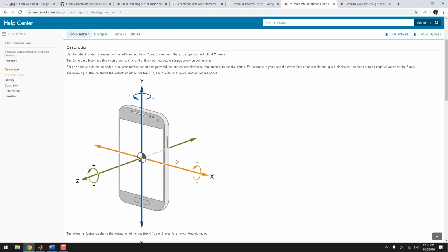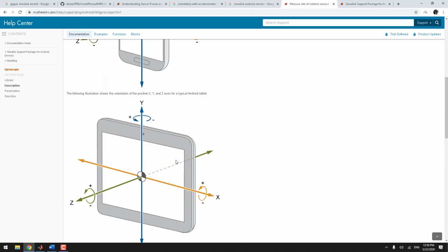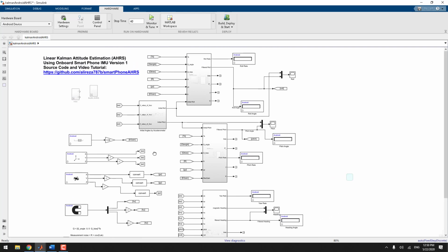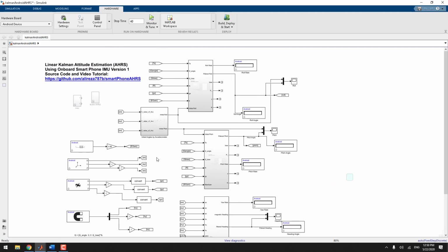So I'm going to rotate twice. We have two rotations. I'm going to reverse the Y and reverse the Z. As you can see, these are the minus ones here from the sensor. Or you can just multiply by a rotation matrix if you know what you're doing. I just kept it simple and put minus signs for the Y and Z axes.